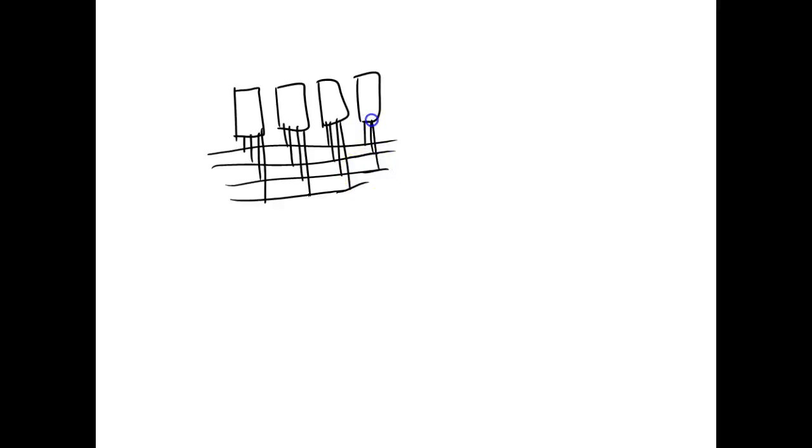This is the way the display on our function generator works. This is a lot of the displays. Most of your cable boxes and stuff like that still use 7-segment LEDs, and that's why it displays those weird characters sometimes. Those are multiplex displays. If you snap a picture on it, you'll see only one of them lit because your camera can catch that. If you take a video of it, depending on the frame rate of your camera, it'll look like it's blinking. What they're doing is multiplexing those displays.